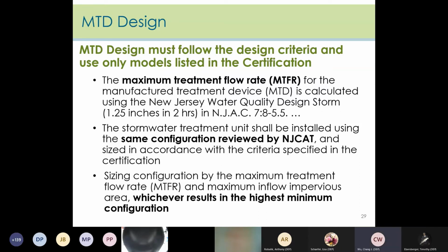Some MTDs are sized not only by the maximum treatment flow rate but also by the maximum inflow impervious area. So you have to do both calculations, and whichever results in the highest minimum configuration, that means you have to choose the model with the higher capacity.